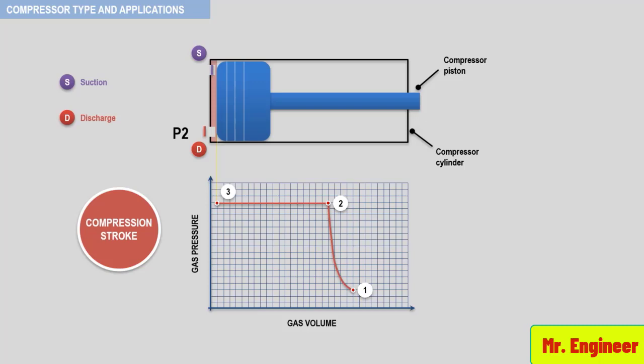When the piston reaches point 3, it has traveled to the upper end of its stroke, also known as the top dead center. Physically, at this point, there is a space between the piston face and the head, as depicted here. This space results in a trapped volume of gas, illustrated in this example in red, and is called the clearance volume.